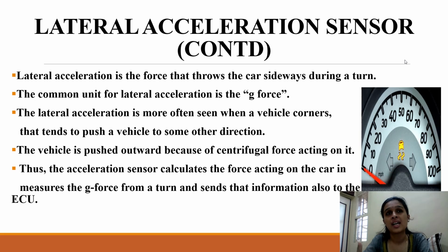So therefore, every time while taking a turn, the driver always experiences some sideways force that is acting on the car. The sensor that takes care of this is the lateral acceleration sensor. The lateral acceleration sensor will always get the information of how much force is acting, and it will send this information to the ECU, which is the stability unit, and then the ECU and the stability unit will take those important measures to stabilize the car.